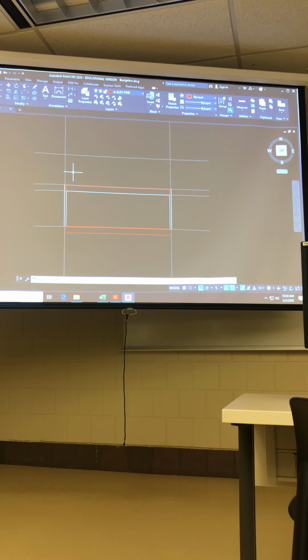Okay, doing okay? So I want to go one step further here in drawing my roof truss before I mirror it to the other side and then start really making it look like the drawing that we're working with. If I go back to my section drawing in the handout, we see that the top chord of the truss actually extends here. It goes beyond the face of the exterior wall, and the tail of the truss is 1 foot 11 inches to the end of the truss from where the outside face of framing is from my exterior wall. Everybody see that dimension?